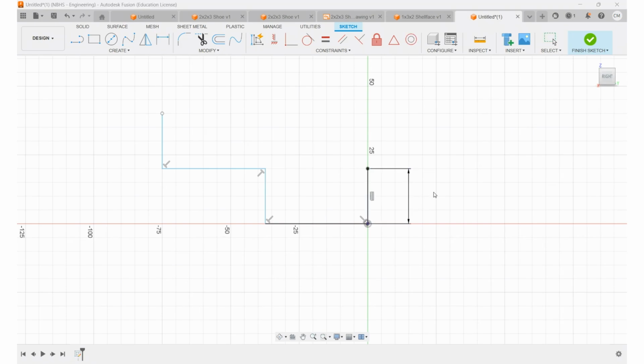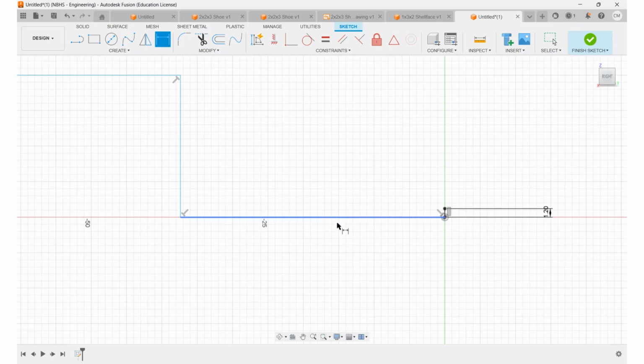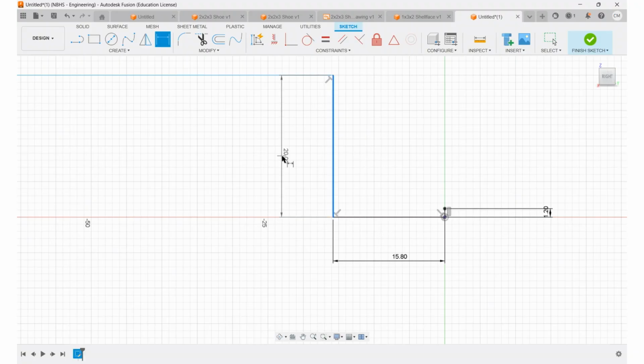All right. Let's break out the dimension tool. So we're going to start with this little flat face. That's going to be our smallest one. That's going to be 1.2 millimeters. That's a constant value in our version of Legos anyway. Now this horizontal is actually going to be 2 studs wide. So remember that's going to be 2 times 8 minus 0.2, which is going to be 15.8. Because I'm not going to generate anything else in this brick, I'm just going to type the values explicitly.